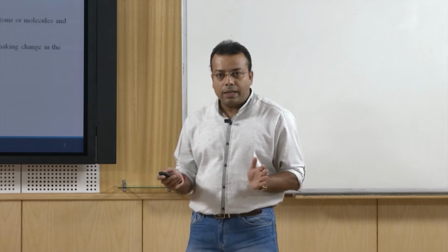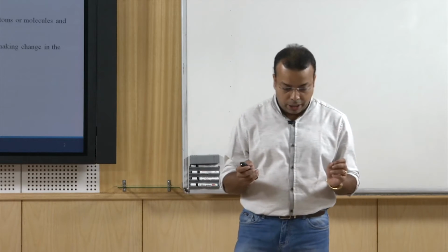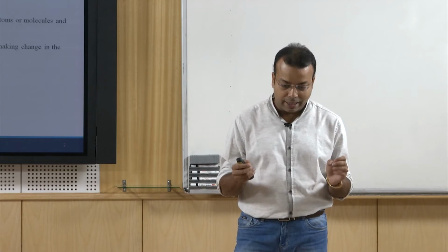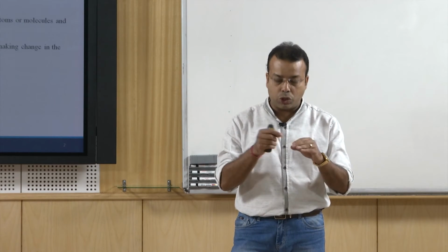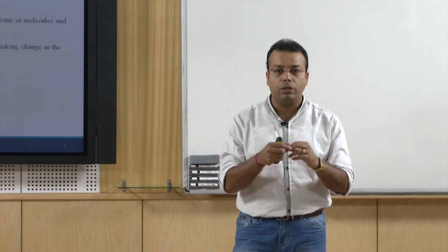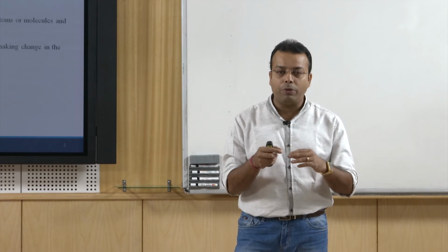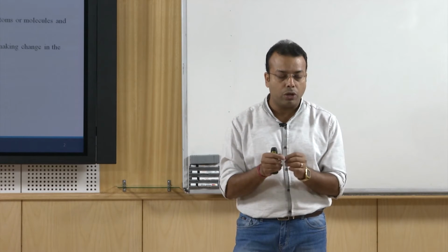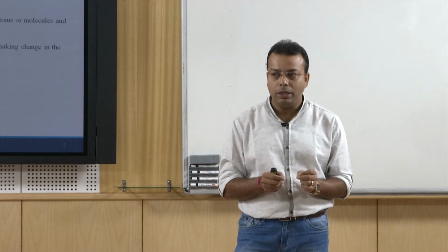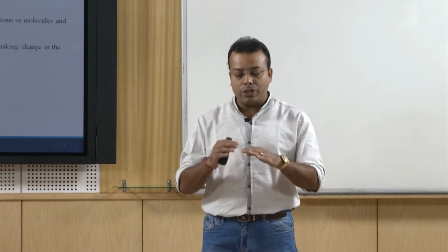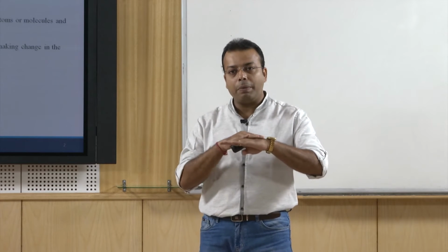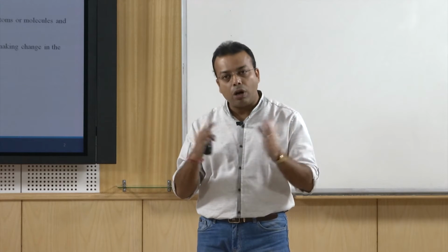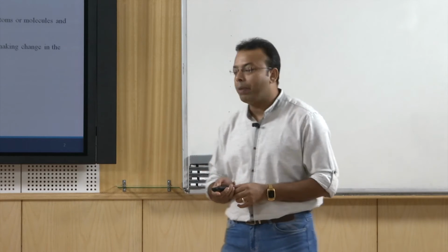So, what is physical modification? In simple words, we can say that physical modification is something like giving a top layer onto the base metal, or putting a coating on the base material. There should not be any chemical reactions between them. Physically, we are just putting a layer or a barrier, so that it will not directly contact the environment.